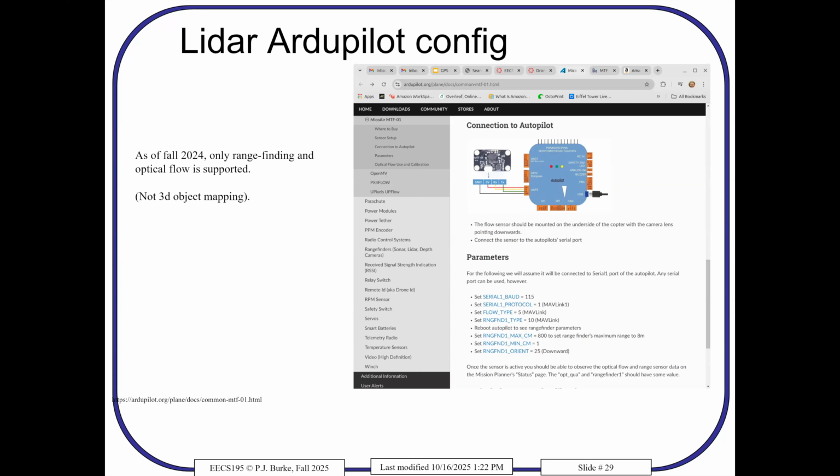So we haven't talked about feedback or state estimation yet. We'll do a theory lecture on that later. But ArduPilot is smart, and it doesn't just rely on one sensor. It relies on many, many different sensors. And if the sensors disagree, it makes some intelligent decision which sensor it should trust. So that's called state estimation. It's a whole field of control theory.